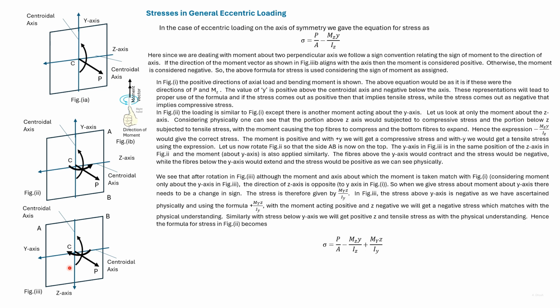Z below the y-axis would be positive. So below the y-axis, we'll get a positive value for this term, which checks out with our physical understanding. For this portion, Z would be negative. Then this term would be negative as well. It checks out with our understanding of compression in this portion.